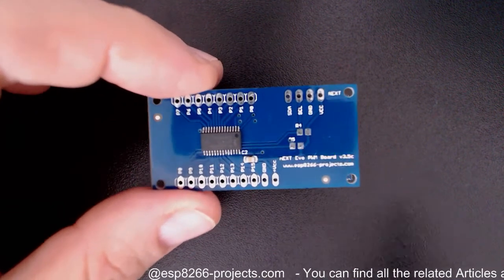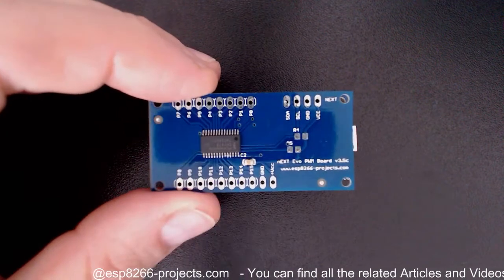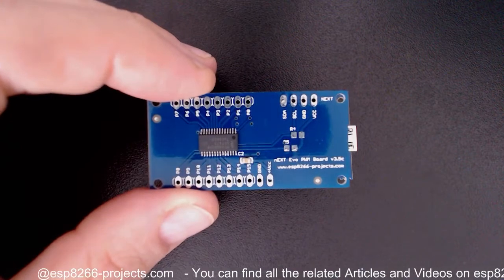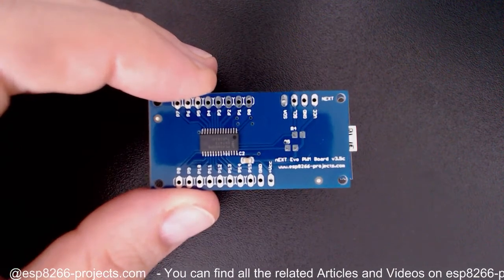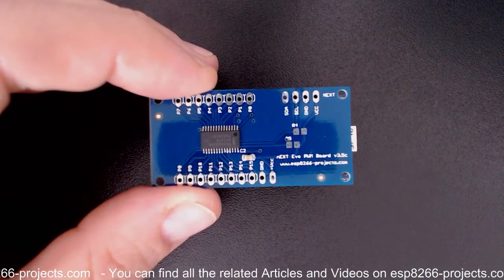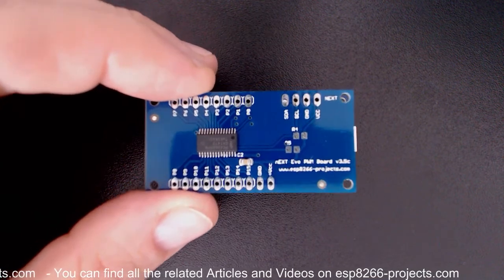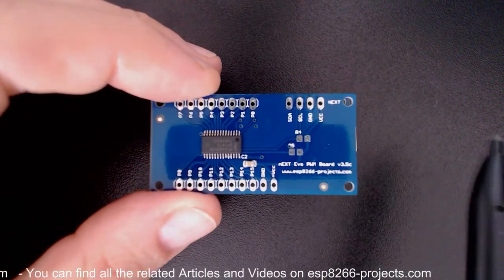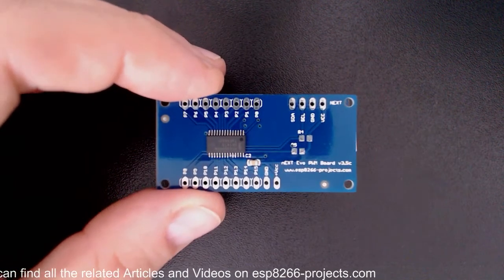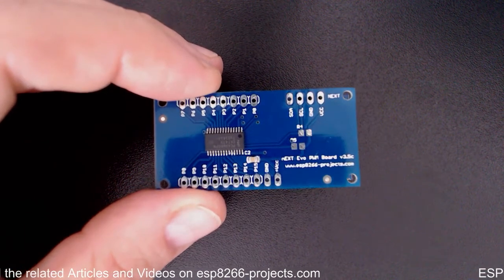As you will see, from these independent PWM channels you can drive LEDs directly. You can also hook up an external MOSFET driver for driving more powerful stuff. And of course, you can use these PWM channels to drive even the MPDM version 4 dimmer board.